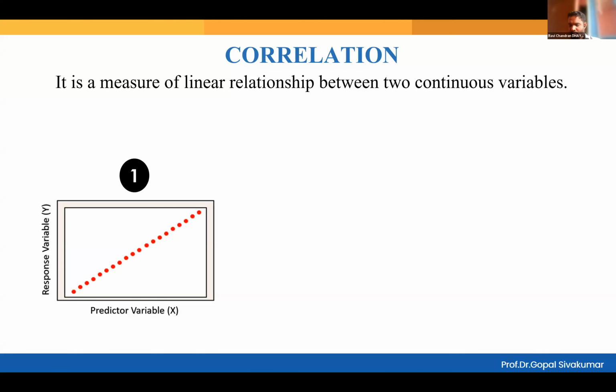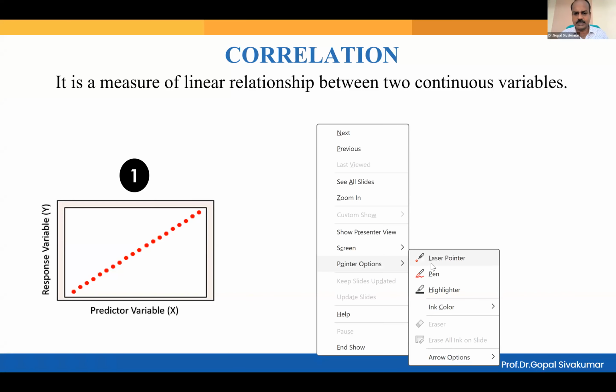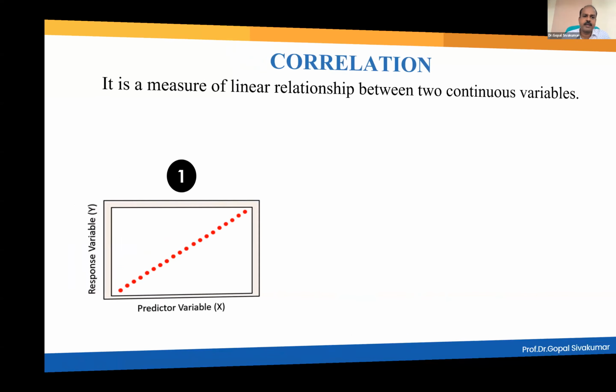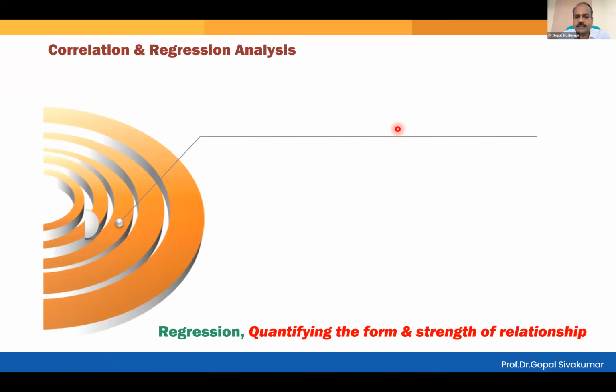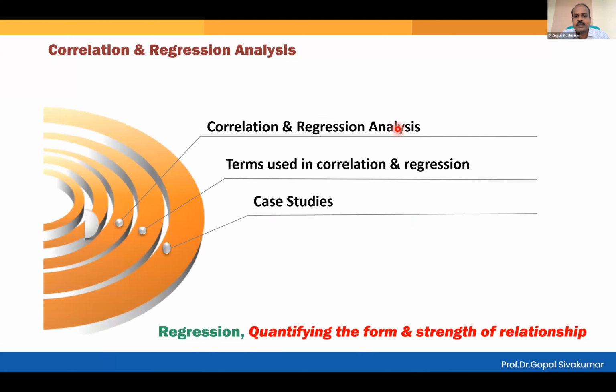So we are going to understand about correlation and regression. The beginning point for correlation and regression is your scatter diagram. You all know scatter diagram, right? Scatter diagram is one of the 7 QC tools, quality control tools. You can use the scatter diagram, or conduct correlation analysis or regression analysis, when both your X and Y are continuous in nature.